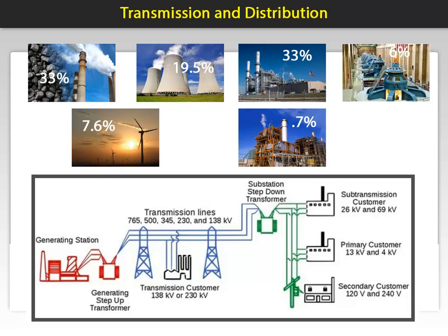Why such a high level? Well, one of the basic principles of electricity is that the higher the voltage, the lower the current. By lowering the current, greater distances can be maintained with less losses and the size of the current carrying conductors can be reduced, thus providing a great savings. At this point of the journey, there may be a large industrial facility with a high electricity demand, such as a manufacturing plant, chemical processing facility, or a large data center, that purchases power at 138 or 230 kV.